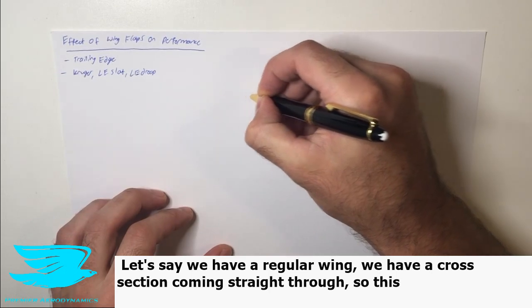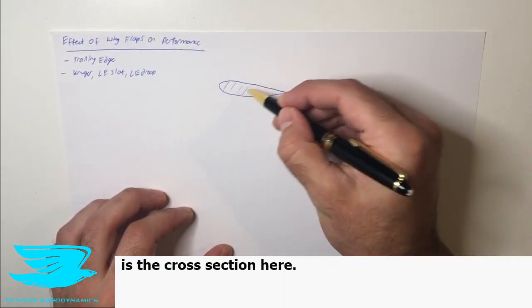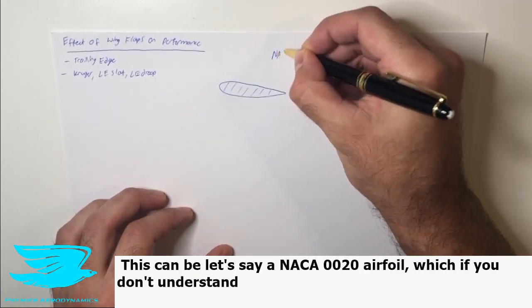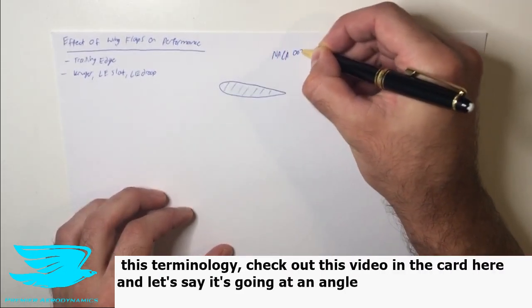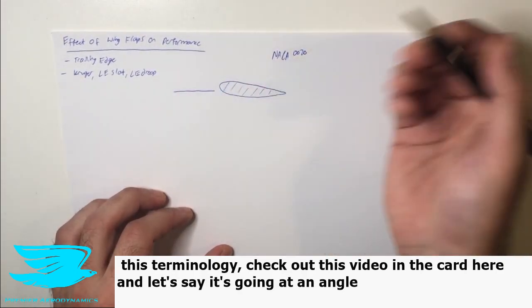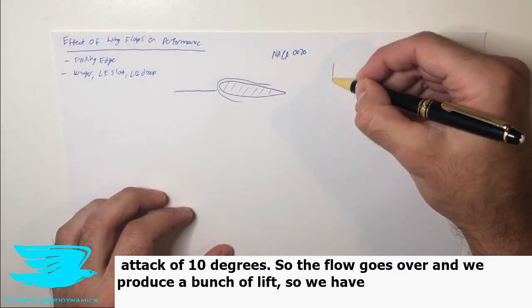Well, let's say we have a regular wing, we have a cross-section cutting straight through. So this is the cross-section here. And this can be, let's say, a NACA 0020 airfoil, which if you don't understand this terminology, check out this video in the card here. And let's say it's going at an angle of attack of 10 degrees. So the flow goes over and we produce a bunch of lift.